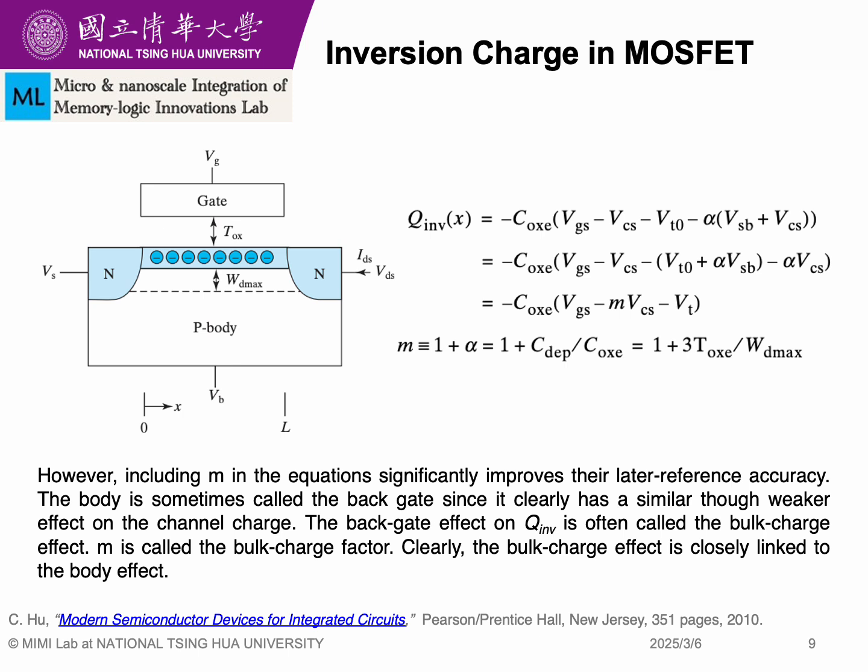Now we can understand the impact on this inversion charge when we apply a source to drain voltage. So what happens? We are moving beyond the simplified scenario where VDS is 0. When VDS is non-zero, you can see here we have some voltage drop from here to here, these 2 points, and the voltage drop is not constant at all points, so it is a function of this length. So the channel voltage becomes a function of position.